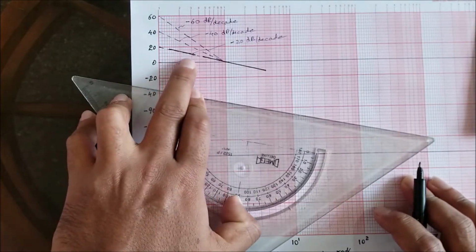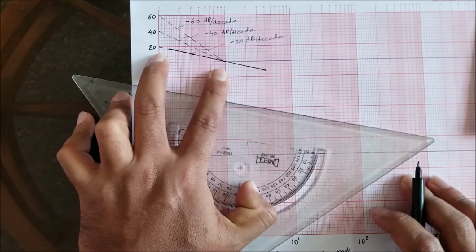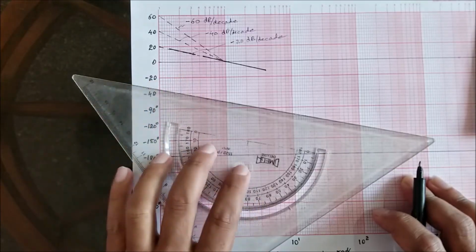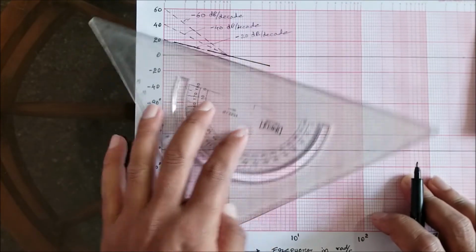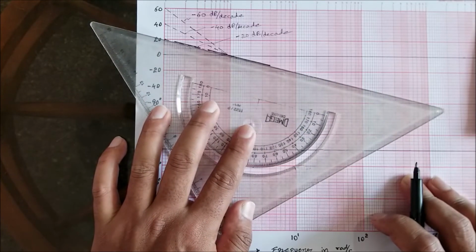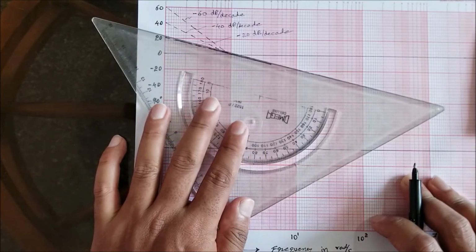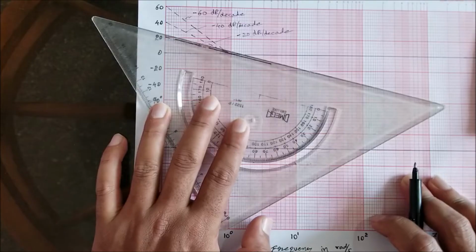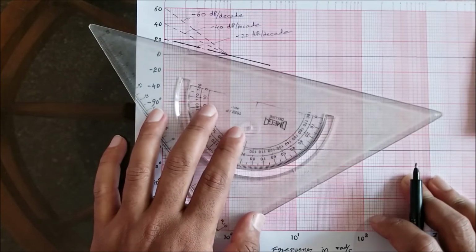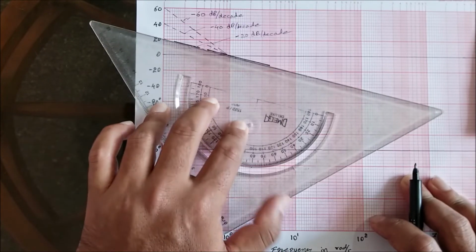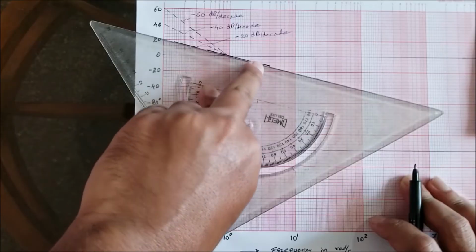That is, the line we generated for minus 20 decibels per decade itself is the starting line, because we don't have a shift of 20 log 10k. If we have a shift of 20 log 10k, then we should draw a parallel line for this in such a way that it shifts to 20 log 10k decibels at 1 radians per second, and that will become the starting point. From that line, for the given range of frequency, we should start the problem. But for this problem, k itself is not known. So therefore, whatever I obtained for minus 20 decibels per decade itself is the starting line, from which I started the problem till 4 radians per second.